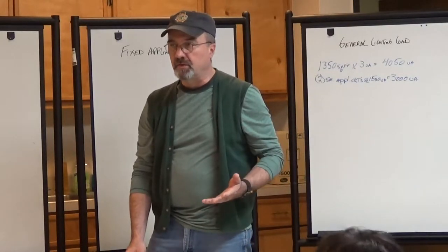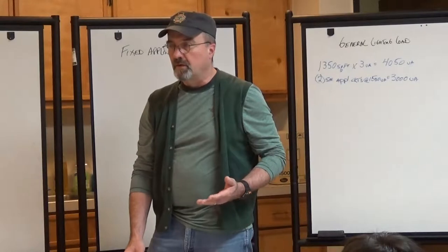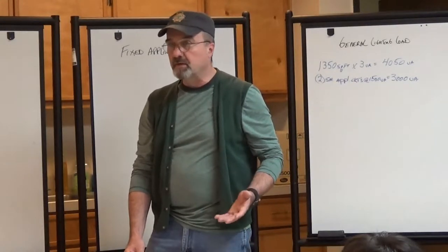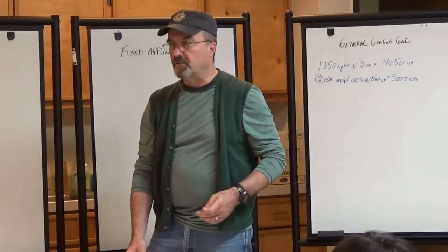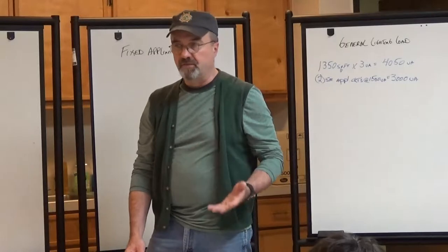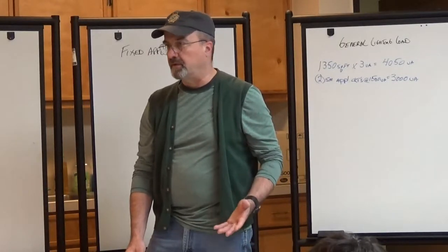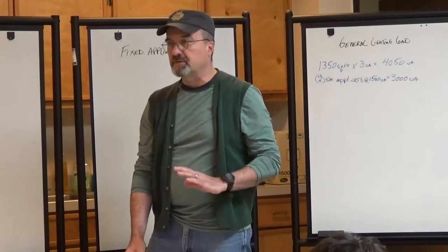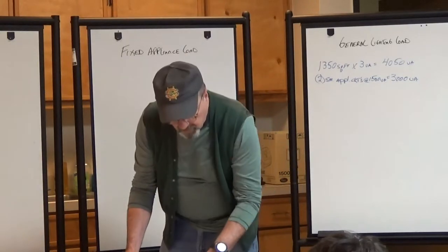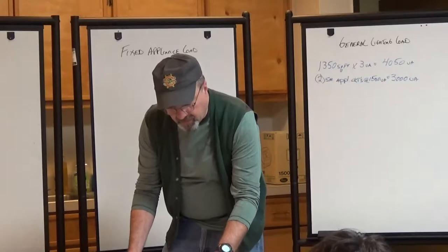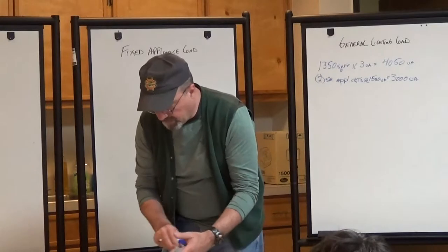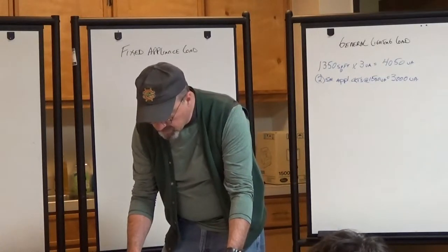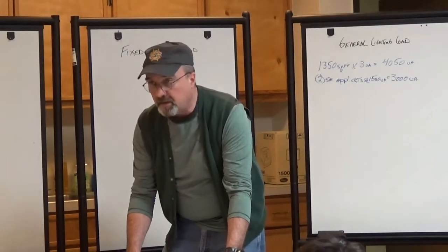Also in the laundry room, often some ironing gets done, and so there is a dedicated circuit for the laundry room that's required by the code, for your washing machine and for ironing your clothes. Nothing else can be tied to that circuit. So we read that in 210.11(C)(2), and then we go over to 220.52(B).